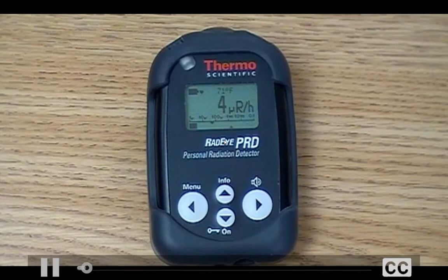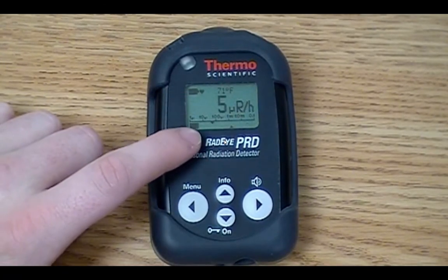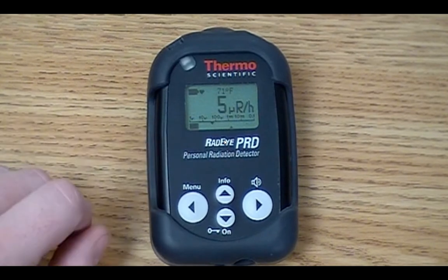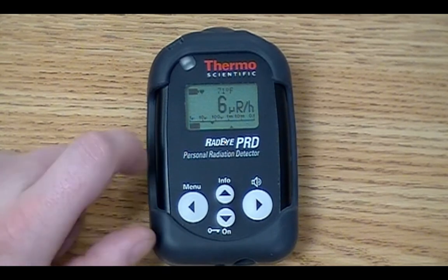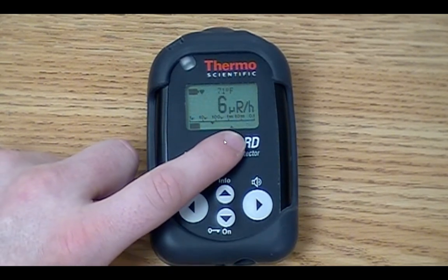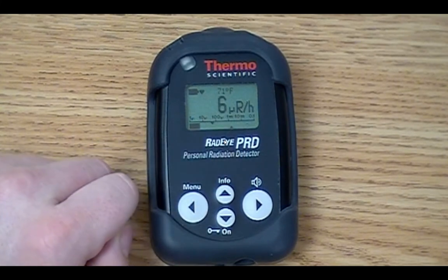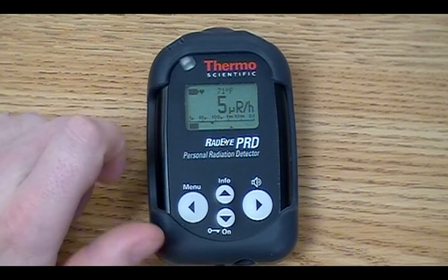The configuration shown here uses the dose rate in R per hour for both the numerical display in the center of the screen and the meter display across the bottom of the screen. Other configurations may show the gamma counts per second, shown as CPS, or alternatively a simple 1 through 9 level value. The downward pointing arrow on the meter represents the Alarm 1 threshold, while the upward pointing arrow represents the Alarm 2 threshold. The battery status is displayed in the upper left corner of the main screen.